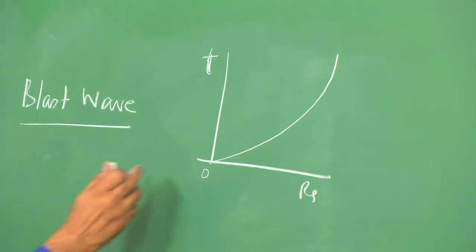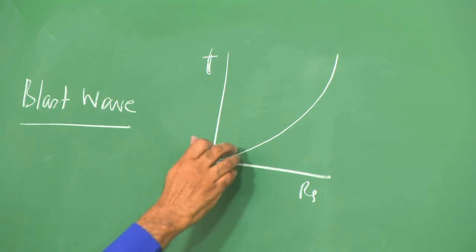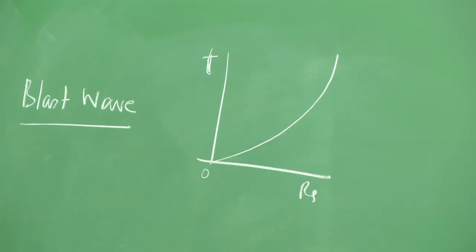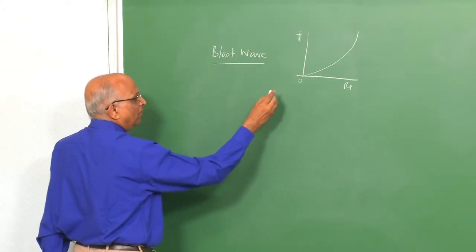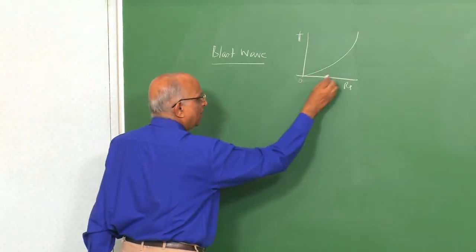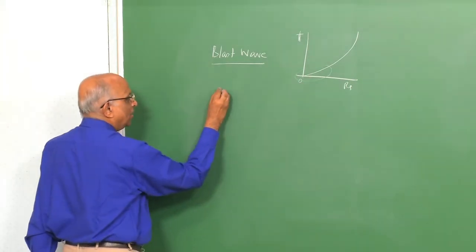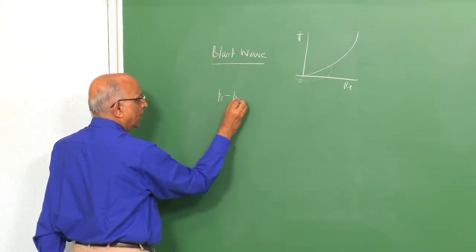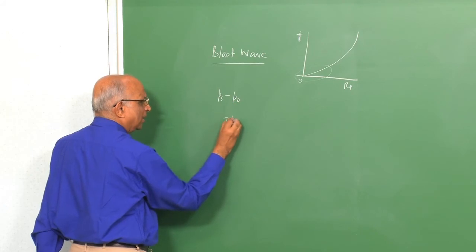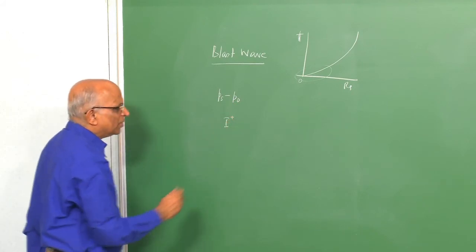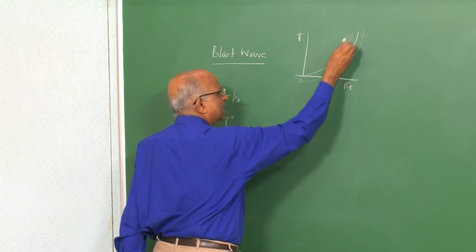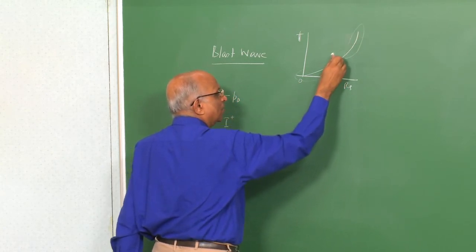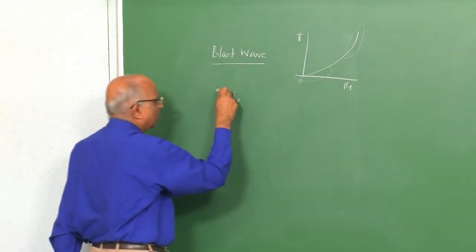We talked in terms of different types. We talked in terms of constant velocity. We were able to get the Mach numbers. Using that, we derived, in the near field, wherein I have a strong blast wave, the value of overpressure. I was also able to calculate the impulses. Similarly, when the blast wave decayed, it decays at values when the Mach numbers are a little lower. I again calculated these values.